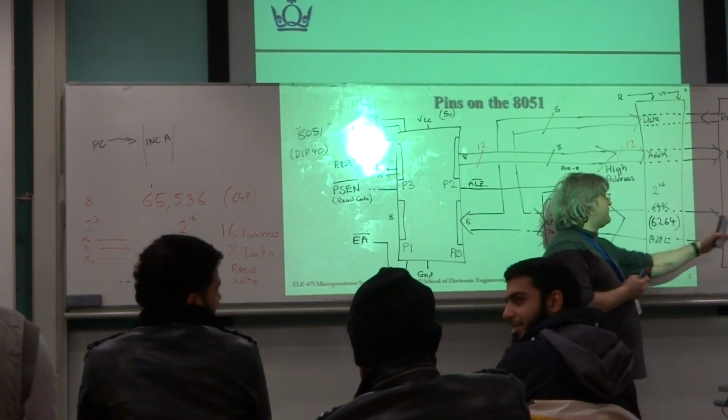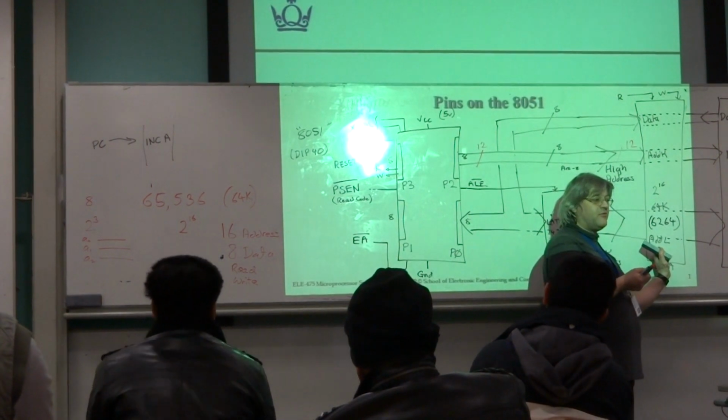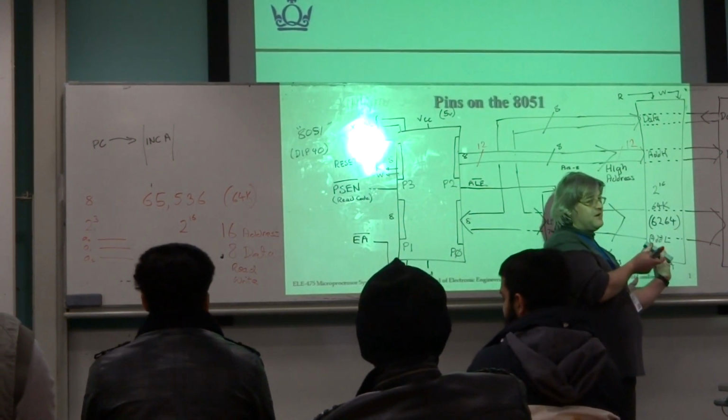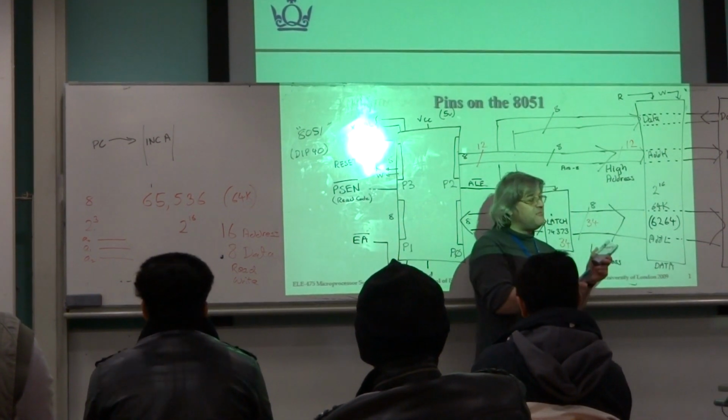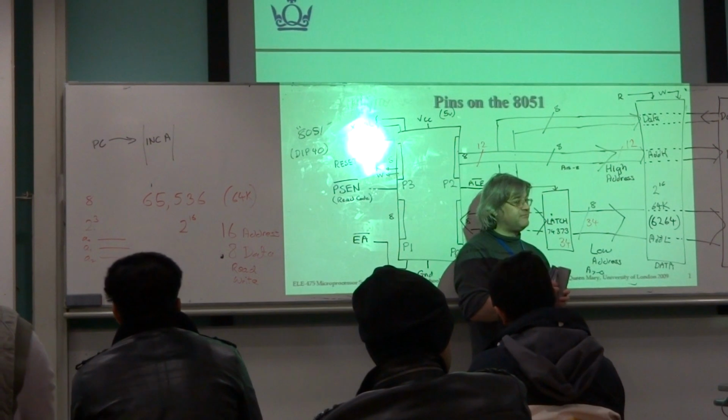The crucial thing is if you use a ROM here, there is no signal to wire up to do a write for ROM. ROMs don't have write signals normally. They have a special program pin, but that's only for programming purposes. There's no means of writing to a ROM. You need a special programmer.